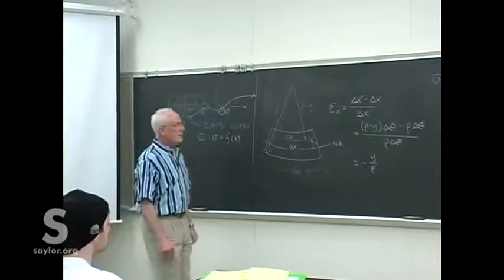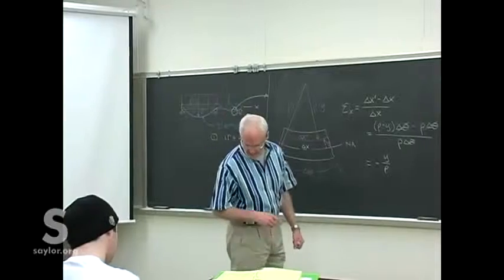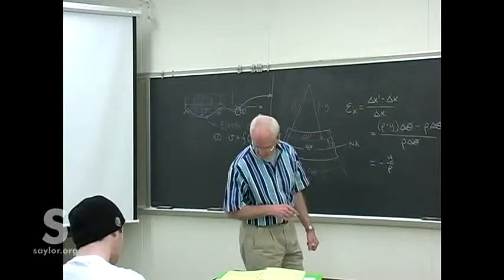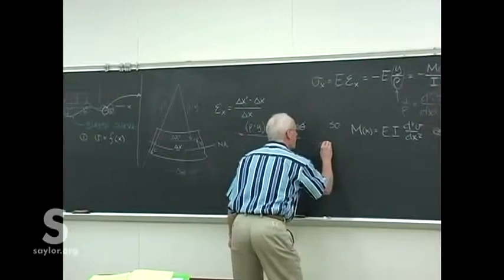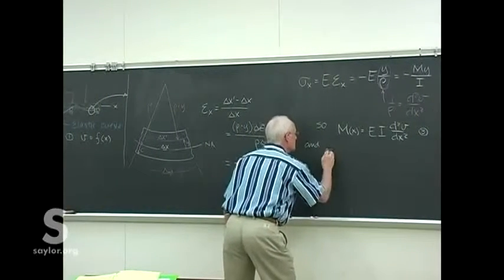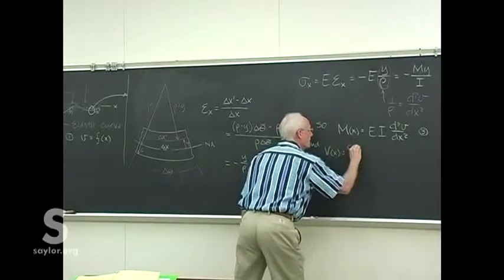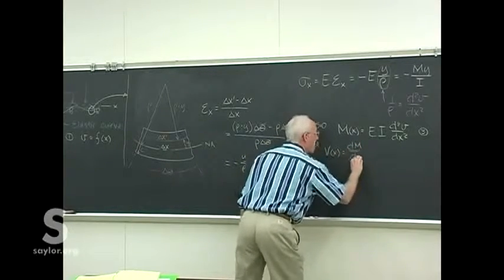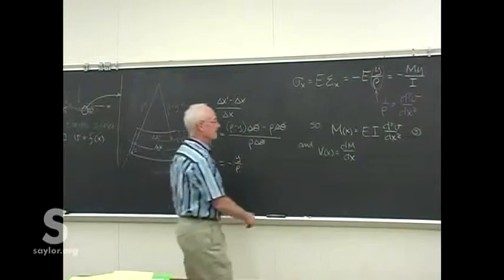But just to be a little bit more complete, let's remember a couple other pieces that we might need. It just depends upon where we are in the problem. We also know that the shear as a function of x is the first derivative of the moment. We use that putting together our shear moment diagrams.